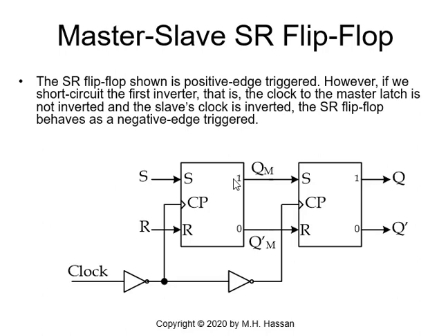It means the change will occur as the clock changes from 0 to 1, or a negative edge trigger will allow me to make the change as the signal changes from 1 to 0, as the clock pulse changes from 1 to 0. So this is the reference. This is what we really call a flip-flop.